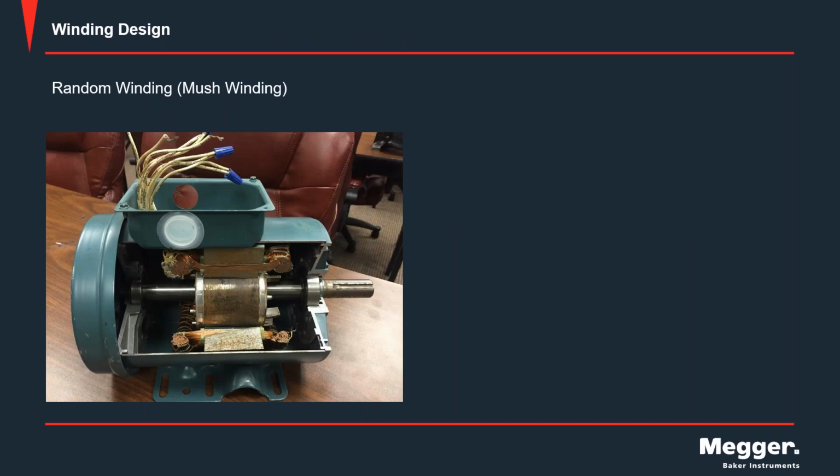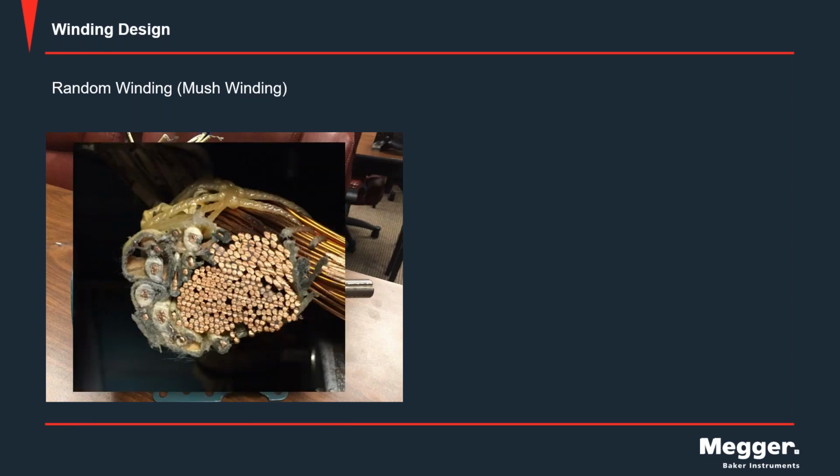So windings can either be random or form wound. Here we see a cutaway of a motor that is a random wound or mush winding. Close up, the coils are just laid down, and in the coil the turns are not formed in any kind of order. Turn 1 might be right next to turn 15, or turn 5. It's random. It's different for each motor of the same type that's constructed. So we have random alignment there in the smaller motors.